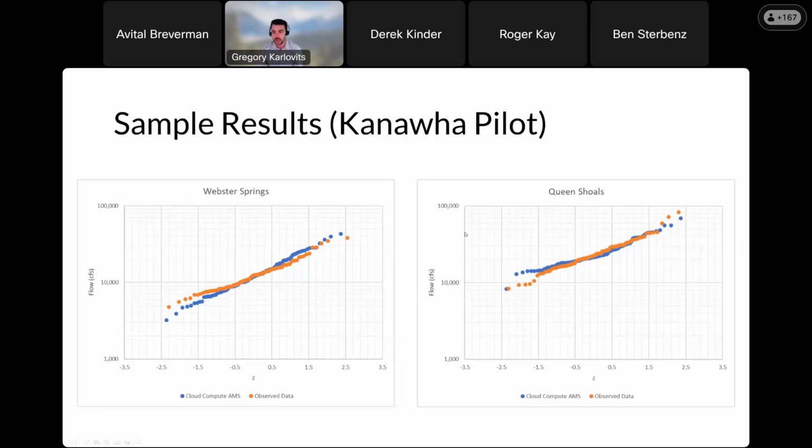A lot of folks, Dave Rosa from FEMA, cover your ears. Most folks are looking at the 100-year flood. That's about 2.3 standard deviations above the mean. That's right in this range here. So we don't have quite the refinement in this region, but what we look at when we see this is that the trajectory of these and the agreement with these is excellent. And for the most part here, what we're looking at is a difference of sample error.